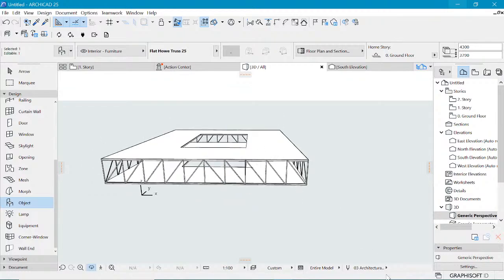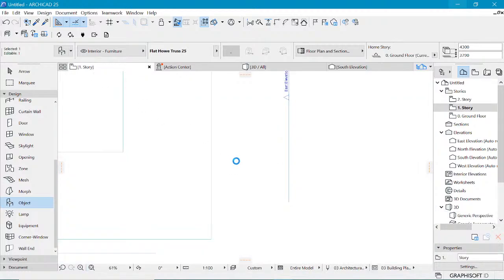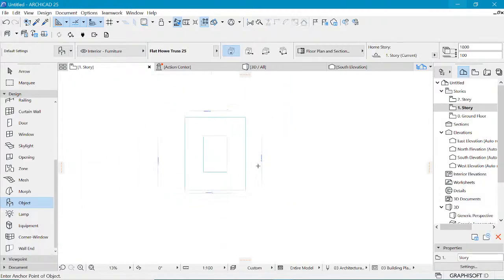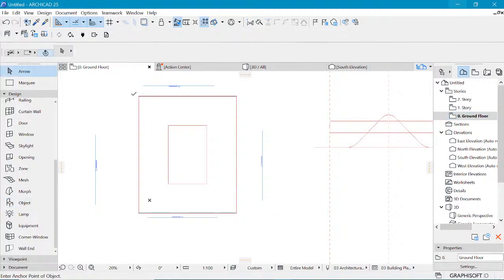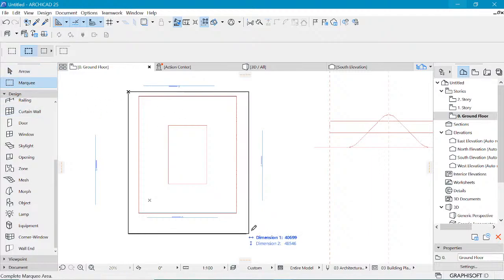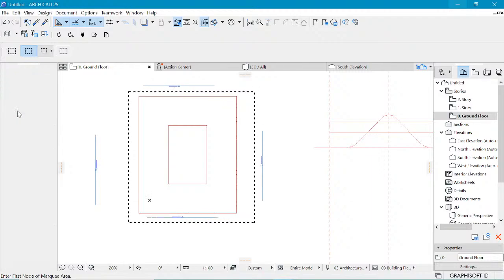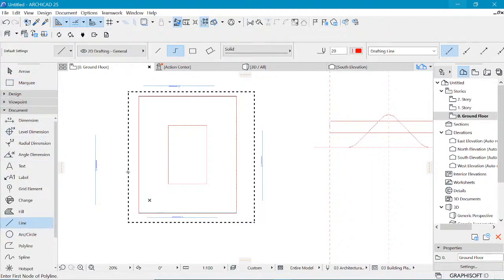Also, we need some of those elements on the inside of this thing. So we need some of those elements in here. You can do that in the first floor. And that's also another thing we need to watch out for, because currently the elements that we have added are on the ground floor. Now let me delete these lines, so you can press Q and then select line. With the line selected, you can select all those lines and delete them. Of course, it was polyline, not line. So let's select these ones and delete them.